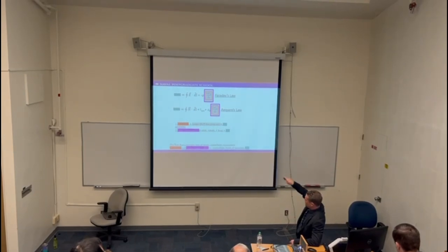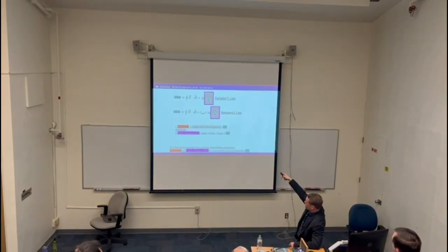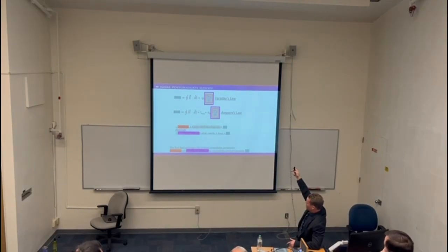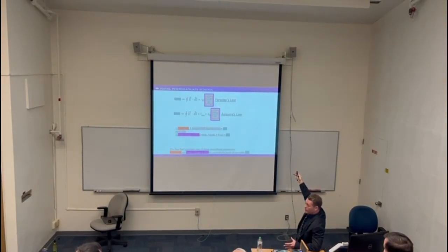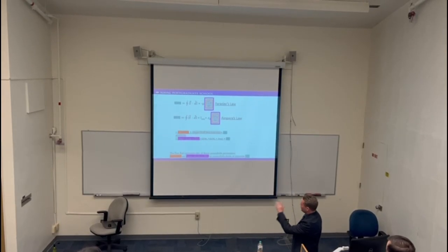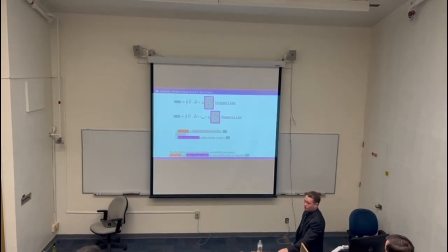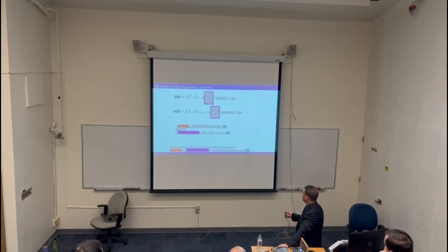So I can essentially, like I said, leverage these terms here. If I have a larger E or H field, they're kind of interchangeable here depending on whether I'm using E or H, I'm going to create more EMI. If I have a larger device under test flux loop size, I'm going to create more EMI. Do I have control over that? Absolutely not. The device under test is what it is. It's locked in stone. That's not one of my knobs I can turn. I certainly can turn the amplitude though, and I can change the frequency. A faster change in flux of my E and H field also produces more EMI. So that is what we leverage.